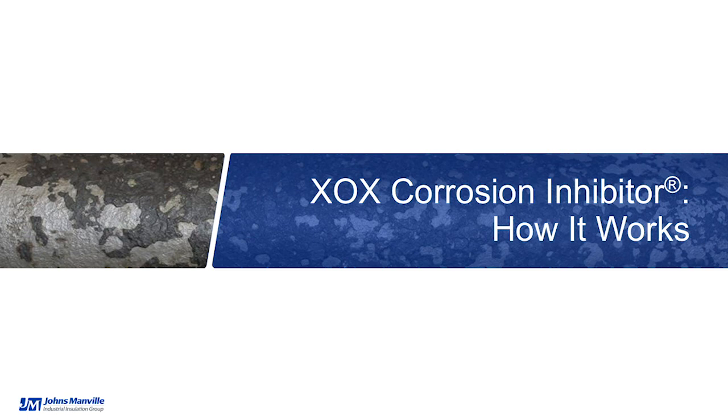The second thing that Juan Carlos covered is that one of the necessary components for corrosion to occur is the presence of water or moisture in the system. Experience tells us that it's a great idea to keep water out of the system as much as possible. That's why there are so many hydrophobic or water-resistant insulations in the market, and why we cover insulation with robust jacketing systems. That being said, we know that water will almost always find a way into the system.